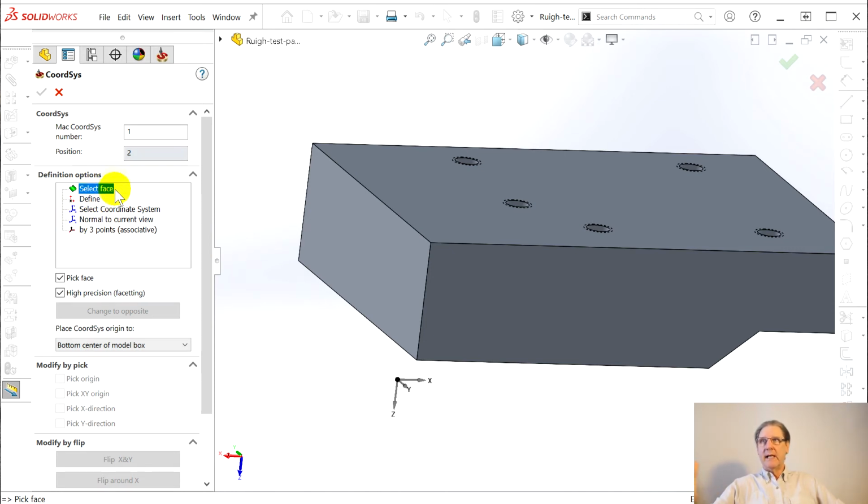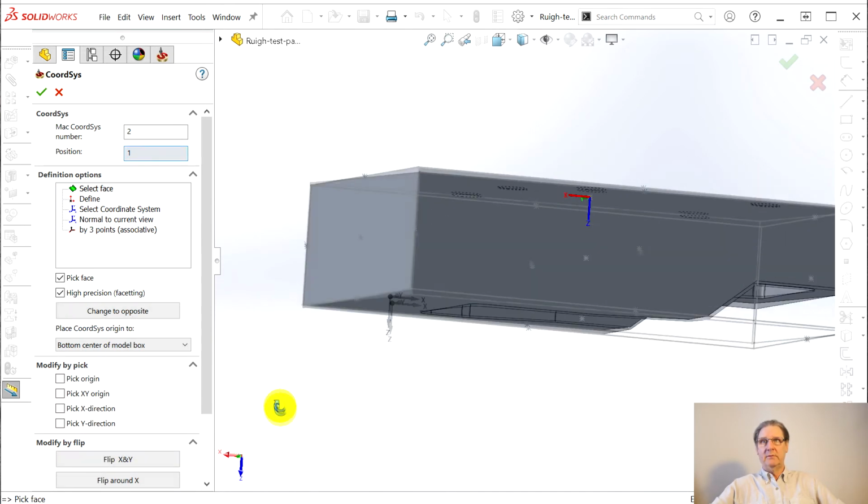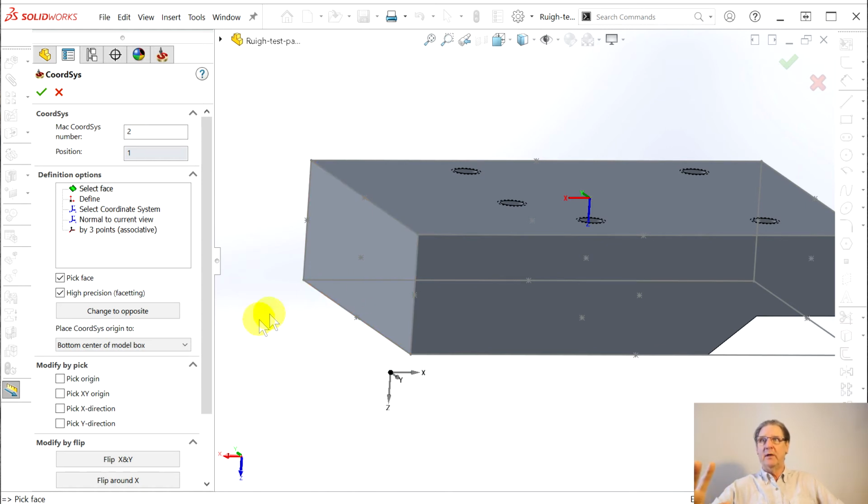This is more exasperation, right? This is what tripped me up so much at the beginning, the first show. You got to know, okay, it wants you to select something because the origin is going to be down here. I learned if you select the top, the plane is going to be wherever you select the origin. Now it lets you select an origin. It's giving you this box, right, with the little asterisk, so you can put an origin there and there. We want to go right here. It defaults to the world coordinate system, not to be confused with the WCS work coordinate system in SolidCAM.